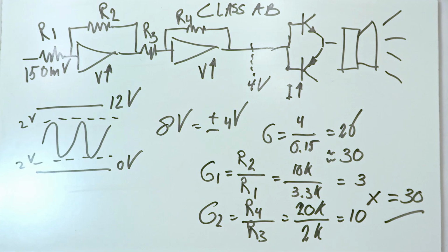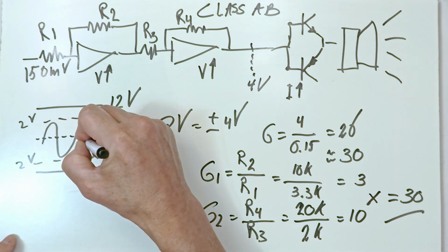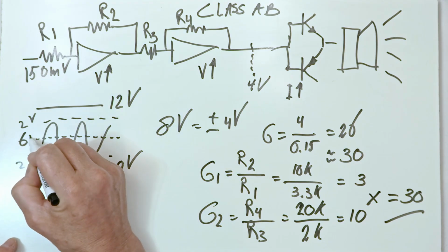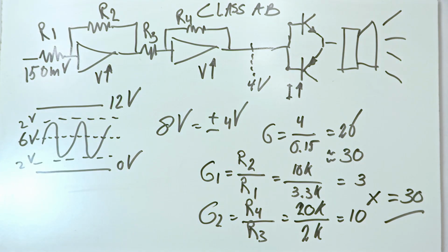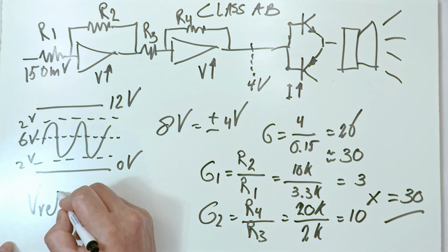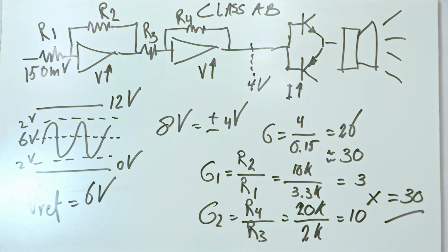The signal swings between 12 volts and 0 volts up and down around a virtual midpoint. This midpoint is of course 6 volts, but it has to be set at the input of the op-amp, so the op-amp can use it as a reference. And because it is used as a reference, it needs to be as stable as possible, just like the 12-volt power supply. But we will dive into that later on. First, let's put this circuit on a breadboard, put some signal into it and see how it performs.